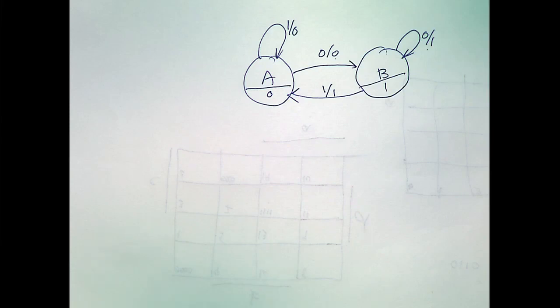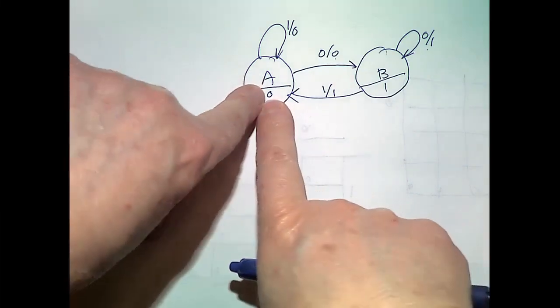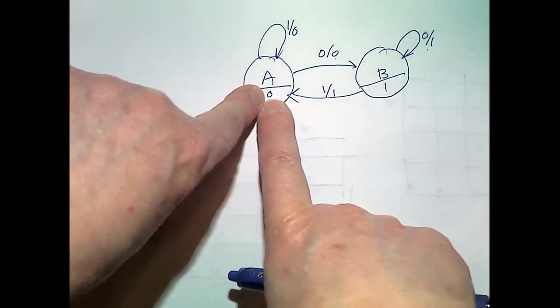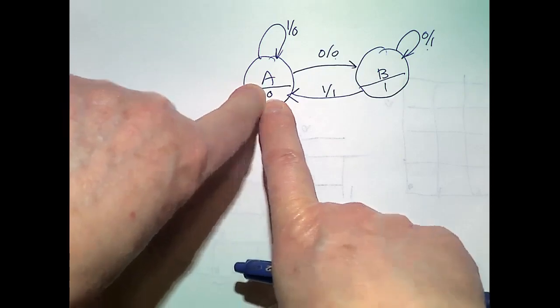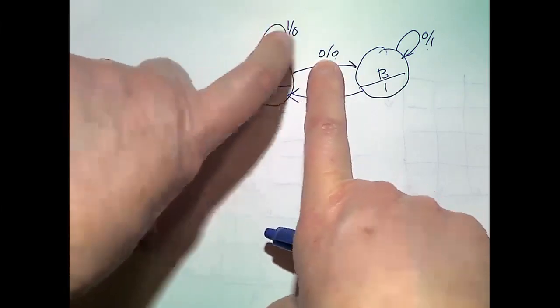Okay? So if we're given an image like the flip-flop and we're told to make the state diagram, either of those is correct? Yeah. Okay. In fact, I think on the midterm too, a lot of people wrote the outputs on the arcs, even though it was a Moore machine, but they wrote them correctly, so that was fine. You understand the difference is that in a particular state, do you need to know the input to know what to output? And the answer is no. You can output 0 either way.